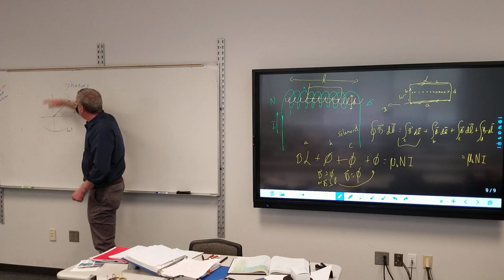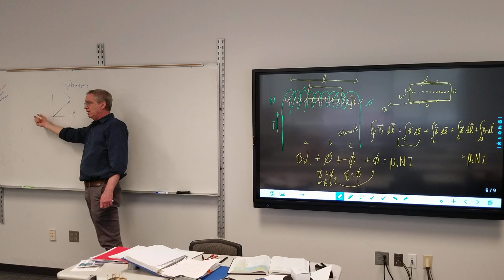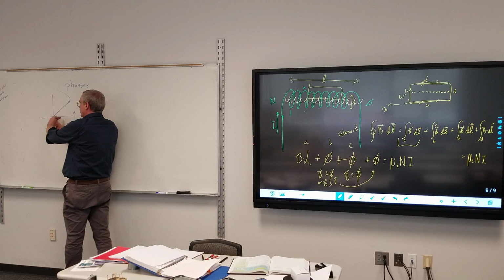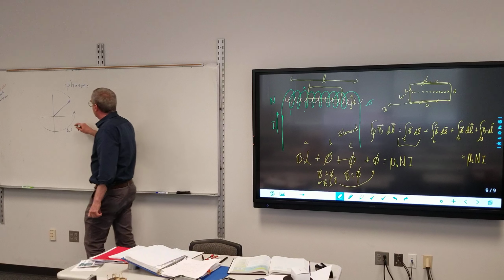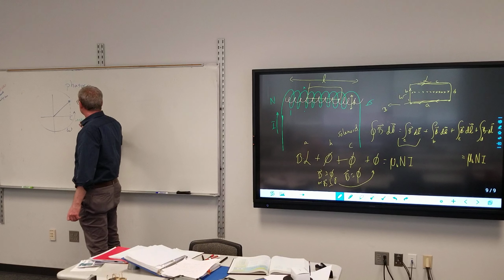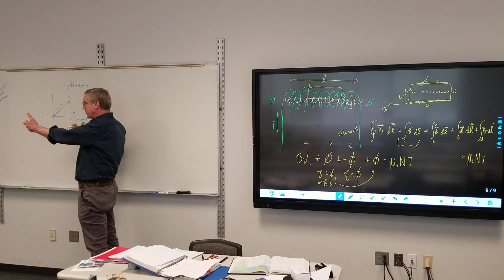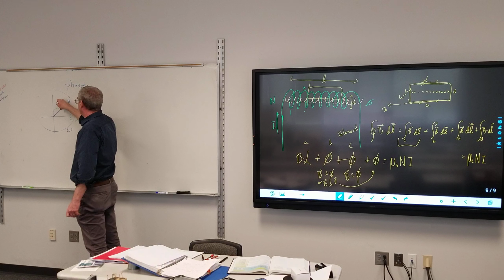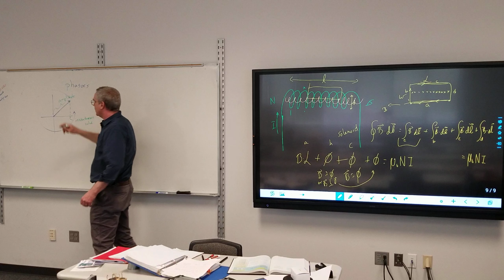If you picture the shadow, and so if I had a light up here as this thing is spinning around, if you picture that there's a shadow on the horizontal axis that starts out here, gets smaller, then goes out here, and the length goes that far, and then it's smaller, then comes out here. And so the shadow length is oscillating back and forth. The length of the shadow is going to be what is known as the instantaneous value. And the length of this is the amplitude. That's the maximum length the shadow can be, when this is horizontal, so the length is the amplitude of the phasor.